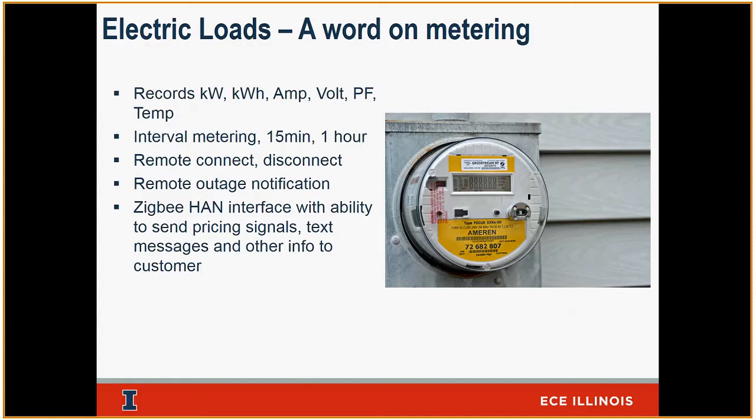Because I don't want to impact the billing time. If it's sending me kWh, I can't send it a profile that conflicts, or the meter will go bazooka. So it's a detailed process: when can you send the new profile to the meter, and when can you start collecting data off of it. It's a little more involved to practically do that. And then again, to store a lot of this data, what do you do with it, where do you massage it, and who has access to it. From a practicality perspective, we are still working through these things.